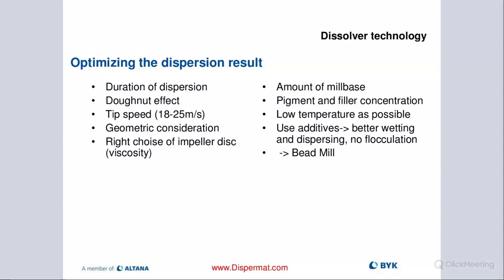Pigment filler concentration, really critical. Okay, what is my loading? Try to optimize that, as we have seen on a previous example where we were putting in only 320 watts of energy, but we were running at 21 meters per second. Maybe that filler concentration or pigment loading was a little bit too low, so maybe we can increase it to have better pre-dispersion results.